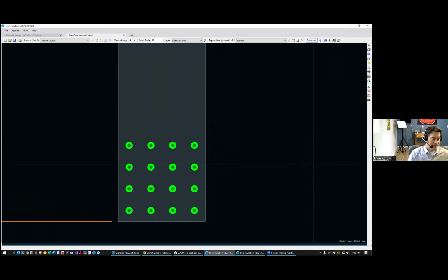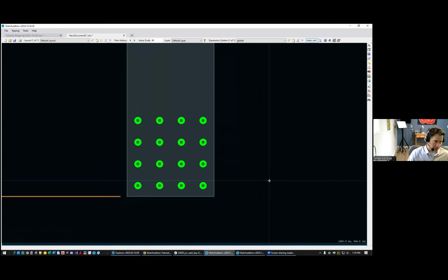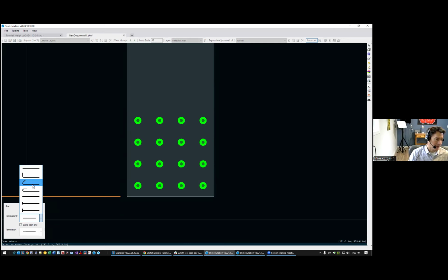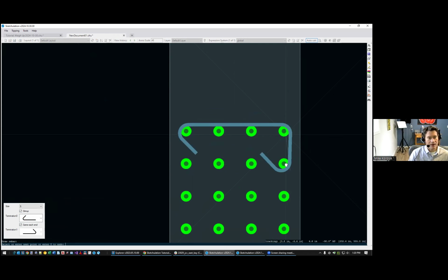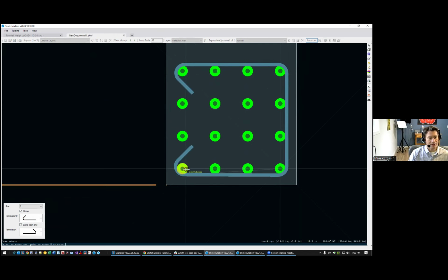And then let's say I want to put in my ties because maybe I want this to look nice and eventually end up in my design. I'll type RB, this time not the S, but just the regular RB. So this will give me a rebar in elevation. Let's say I'm going to need number 5 bars. It's a stirrup, so it'll use the stirrup bend radii. And I'm going to hook it at each end like that. And this is cool. I can just snap to the bar and it's going to wrap around these bars as I draw my cage like that.